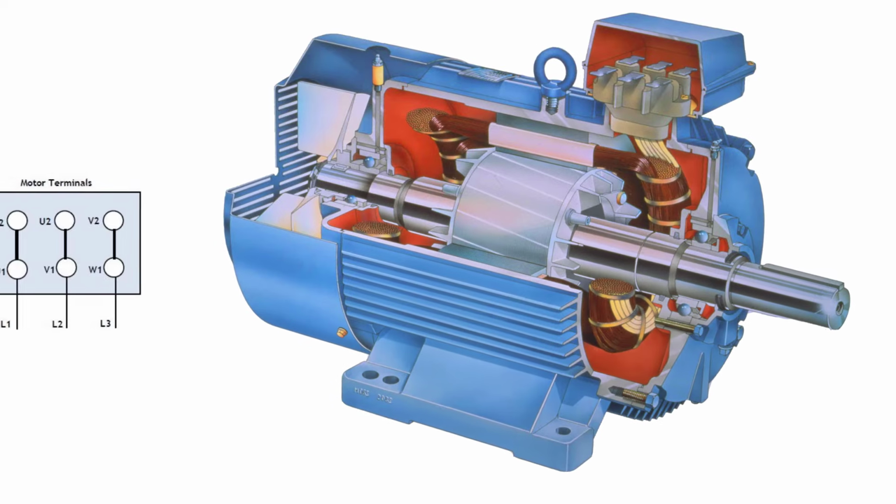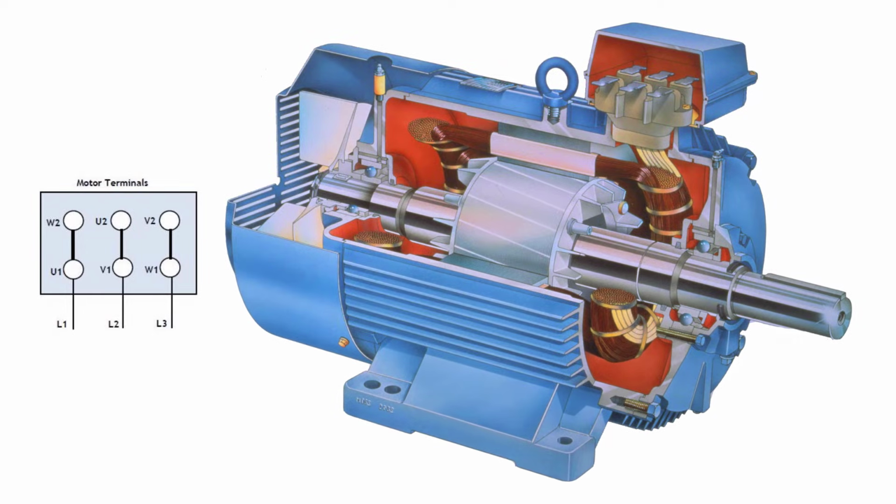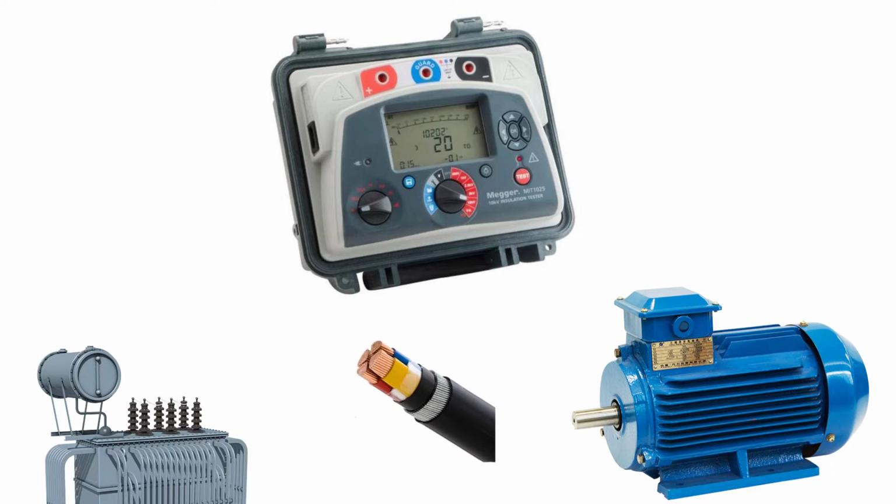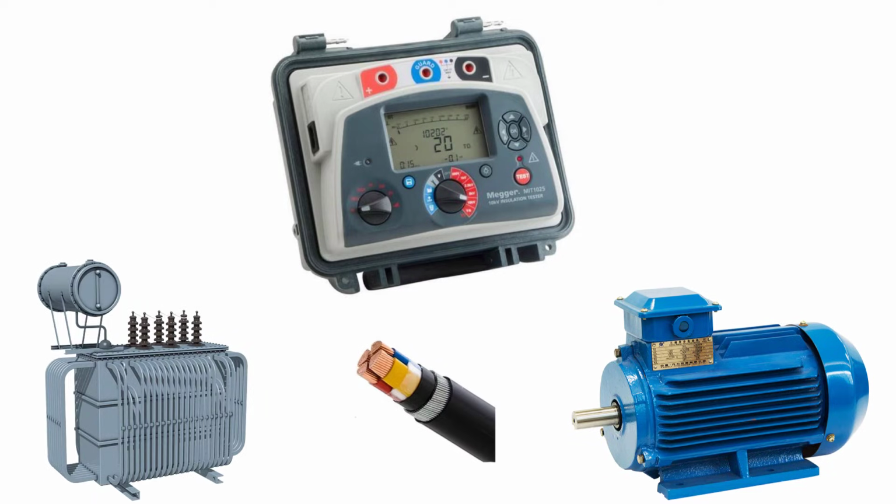We assume that every electrical equipment is well insulated, which means that the body is not in contact with live conductors. But age, harsh environment, chemical contamination, and high ambient temperature can cause insulation performance deterioration. So, we use an insulation tester to detect the insulation level of every machine, cable, transformer, and more.